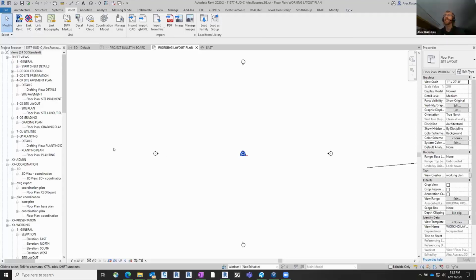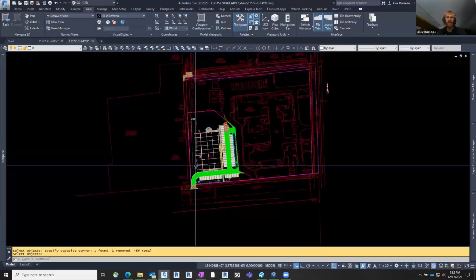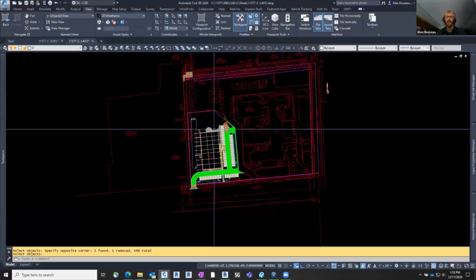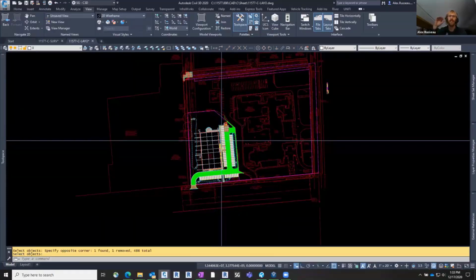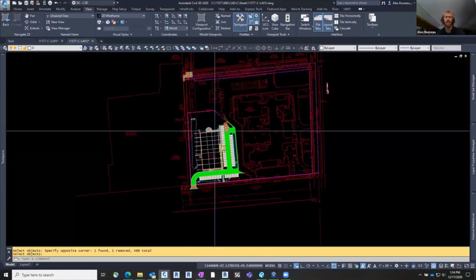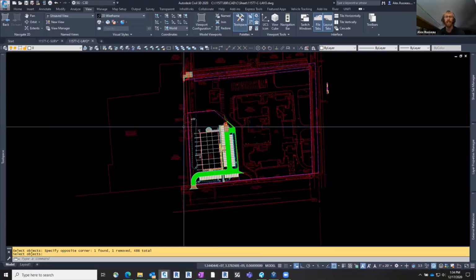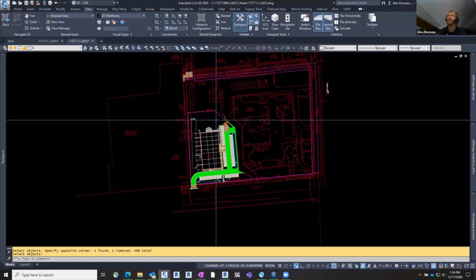Okay. Yeah, I mean, that's honestly what typically could happen with a CAD file: oftentimes all the line work is drawn at zero elevation, but the surface elements such as contours are going to hover up high. So as long as the surface style is set up in Civil 3D to show your contours, when you export that, the contours will still be shown. They're just going to be polylines at that point. So they'll have an elevation associated with them. When you bring it into Revit, they'll actually have the true elevation, whereas all the line work will be down at elevation 0.